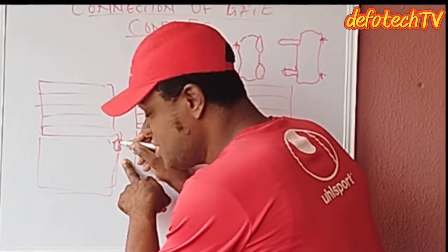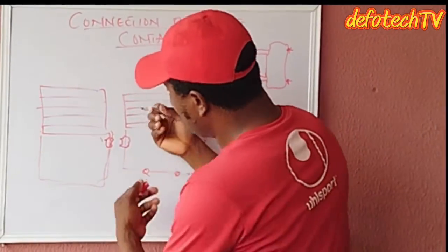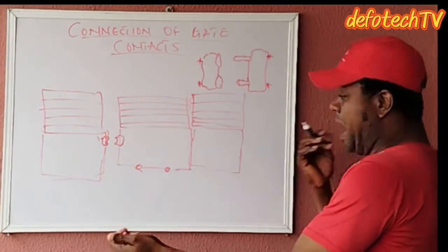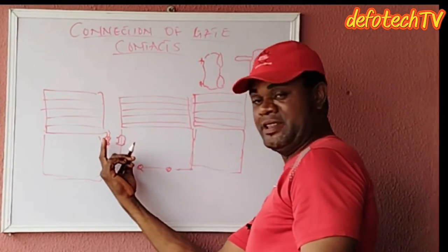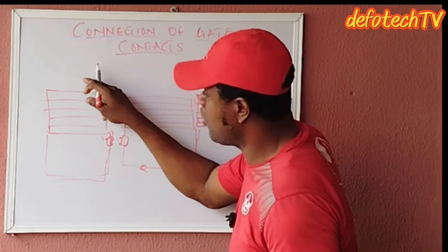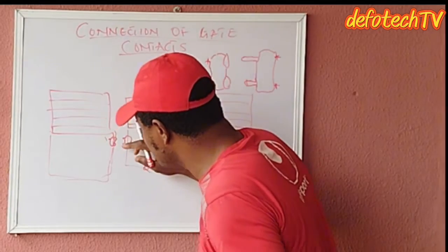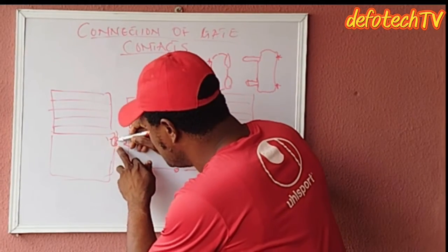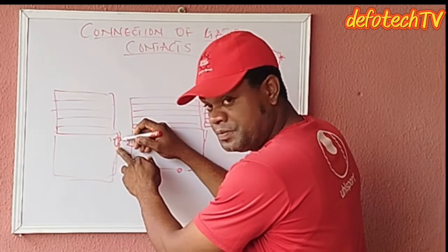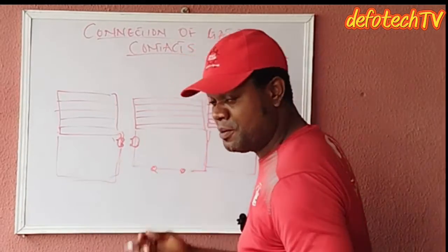It comes, it pushes this one in, and takes connection to this one. The way this gate contact is designed is such that immediately this one moves out, this one draws back, the spring pushes in, and then closes the contact coming to this part. But immediately it comes this other way, this one pushes it, it transfers this close, this contact here automatically becomes normally open.